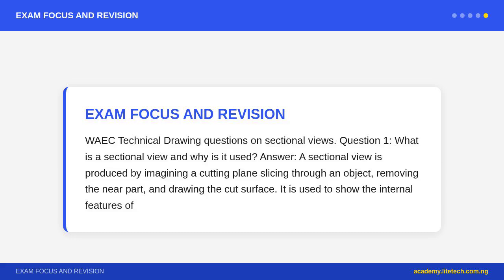Question 4. Why are bolts, nuts, and solid shafts generally not hatched in assembly sections, even when the cutting plane passes through them? Answer. This is the conventional practice for parts that are not significantly improved in clarity by hatching, and where solid hatching could be misleading about the material distribution. Bolts, nuts, and keys are standard fasteners whose cross-sections are already known from their standard specifications. Shafts are solid throughout and section hatching would simply show a solid filled circle. The convention improves readability by reducing unnecessary ink.